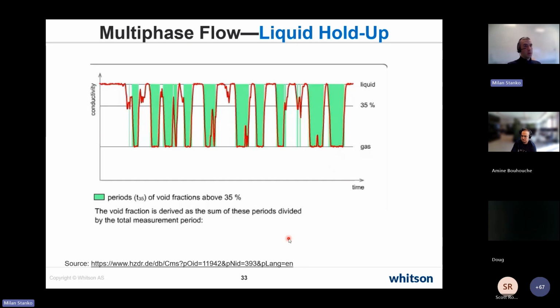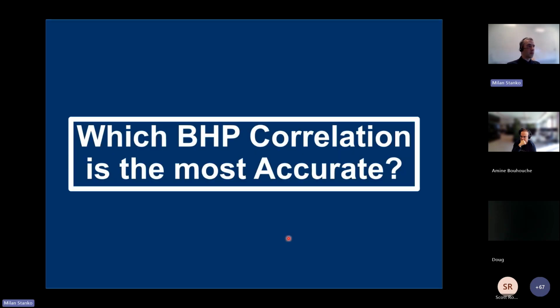This is liquid holdup, but we also have something we can call gas holdup. It's the same: it's how much of the cross section is occupied by gas, the area occupied by gas. But it's more correct to call it void fraction. Void fraction because there is something missing, and that something missing people refer to as gas. But all of them refer to the same thing.